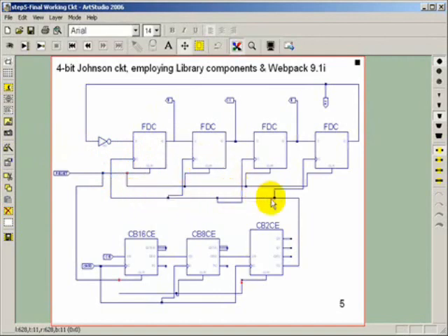We connect all the clock inputs, synchronously toggled by the timer complete output of the division chain of the clock. We will connect the clear line of the counter as well as the 4 data flip-flops to a reset input.